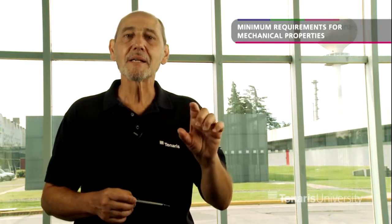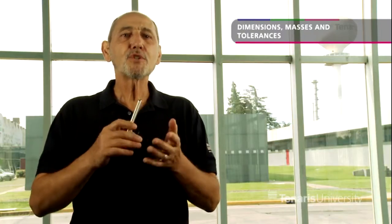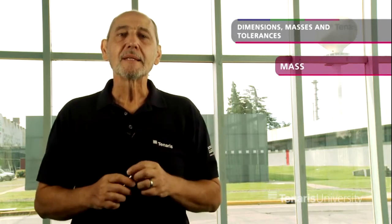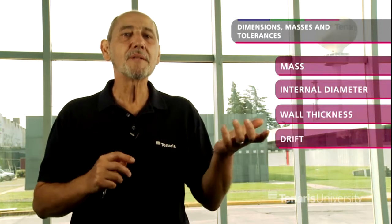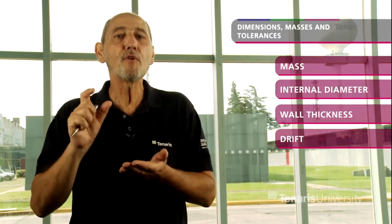Additionally, to guarantee homogeneous heat treatment for high-strength materials, the hardness variation in the wall thickness is required to be within a defined range. Talking about dimensions, masses, and tolerances, for each OD, the mass, the internal diameter, the wall thickness, and the drift are specified for the different nominal lineal masses. Moreover, 3 length ranges are established for the different pipe applications.